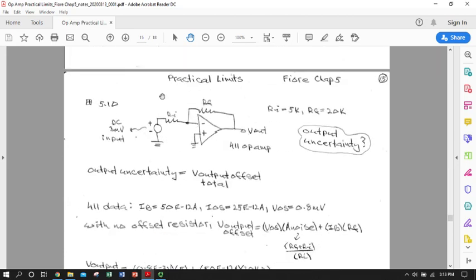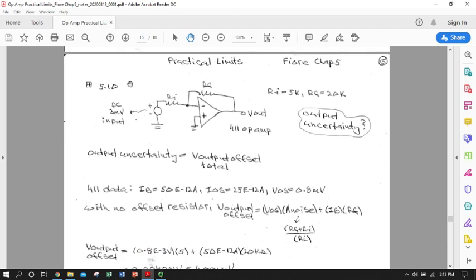So we've got one more example that really cinches the idea of how this relates to error. This is Fiori example 5.10. In this case we have a 3 millivolt input signal. This is very tiny. It's a DC signal. This is the kind of thing you would see coming in off of maybe a strain gauge or some kind of resistive temperature device, or it's probably bigger than what you'd see from a thermocouple. So a lot of very critical, ordinary, everyday measurement methods will produce signals in this range. That's definitely par for the course for DC instrument signals, which you'll need all the time.